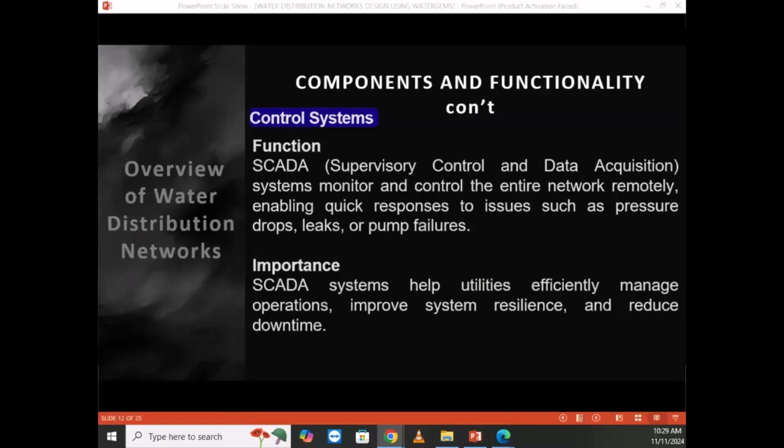During this 100 meters, there may be a small hill, and as water goes, it is losing energy. Based on the calculation for 25 meters, the head losses are very minimized, while if you take 100 meters or 200 meters, the head loss is increased a lot. So it's recommended to take head losses from short distances instead of long distances.